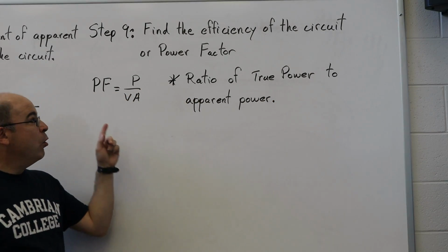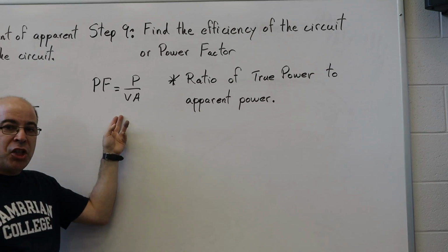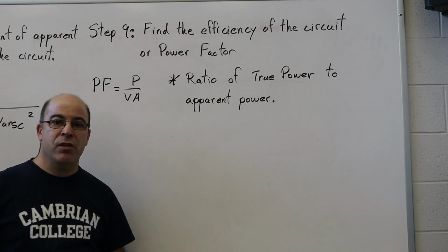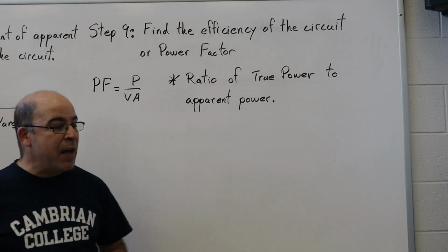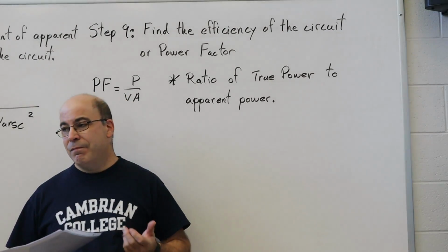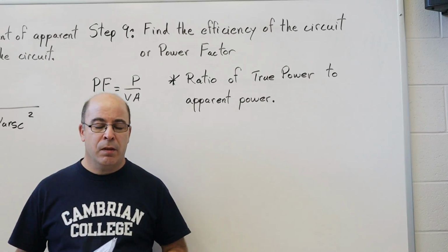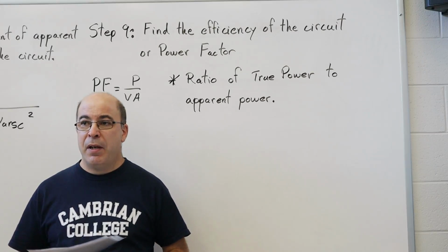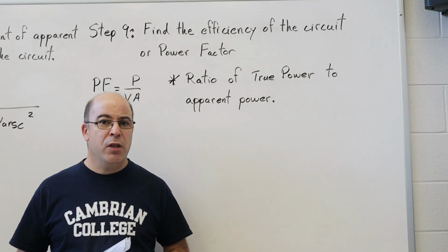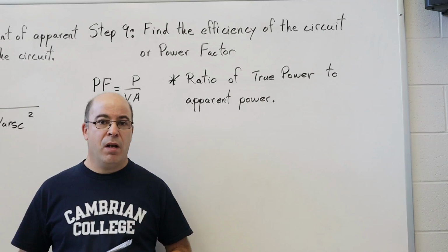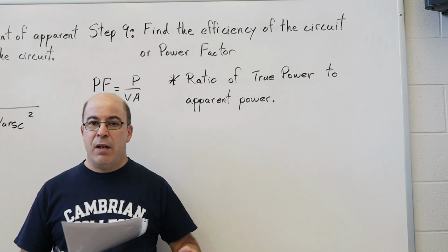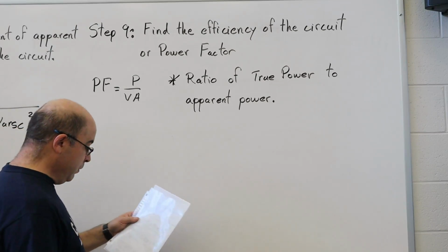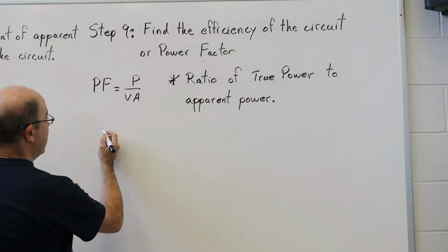Working from power, I always use the same formula, and it does not change whether I'm working with a series circuit, a parallel circuit, or a combination circuit. If we start using values of voltage, it changes because I'm working with a series circuit. If I was working with a parallel circuit, that formula wouldn't function. I'd have to use the current draw of each of the branches. And so in order to keep things simple, I've always worked from power. Now, that being said, let's put in our values.